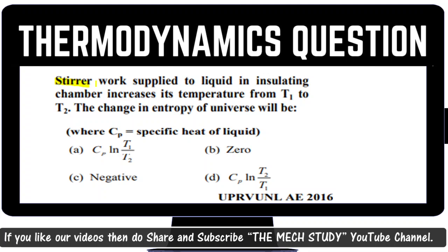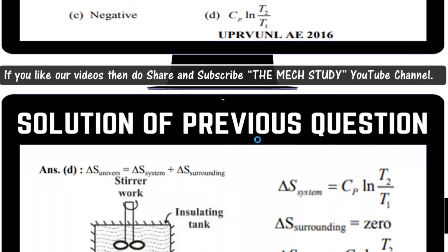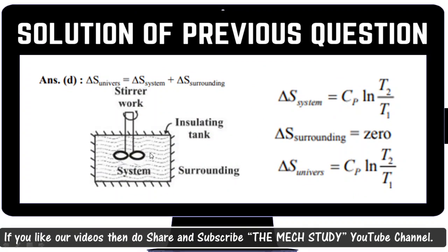So in this question, stirrer work applied to a liquid in an insulating chamber increases its temperature from T1 to T2. Like one chamber is there and it is insulated, and the liquid temperature increases from T1 to T2. You need to calculate the entropy change of the universe, where they have given Cp as the specific heat of the liquid. They have given 4 options. If you have already solved this type of question, then you have an idea how you can approach these questions. But for your shortcut, I'll just explain it to you.